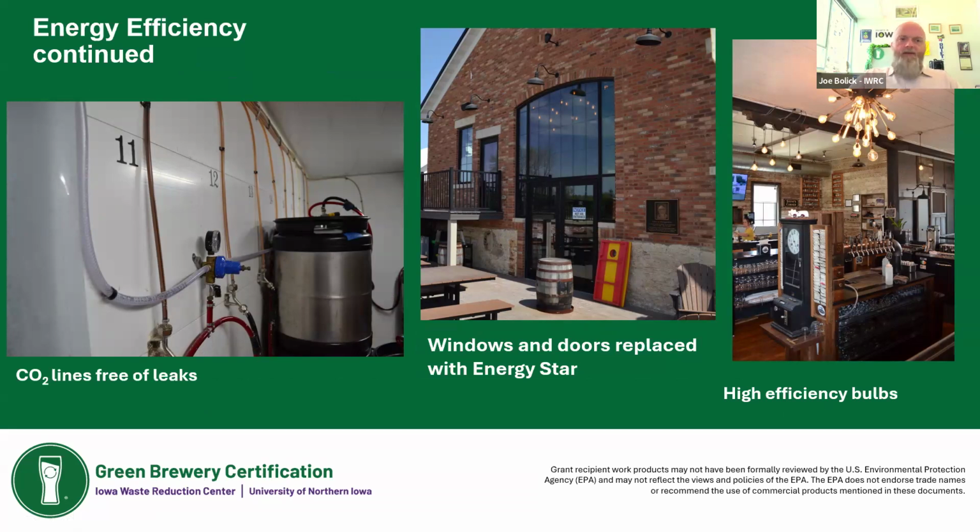So you calibrate it at ambient, and then you can take it and it kind of sniffs through everything. What we'll do is, especially in the coolers, along all of the tap lines that are coming out of kegs, or if they have them in the bright tanks, we'll start usually right at the CO2 tank, and then we'll check all fittings, all of the couplings and fittings along the way, and test for leaks.